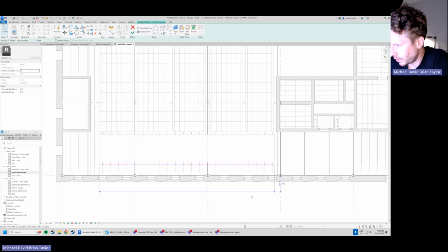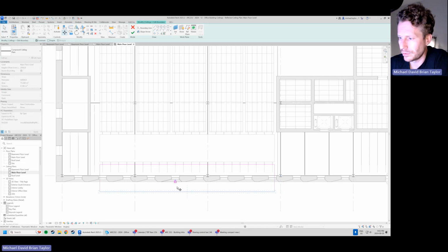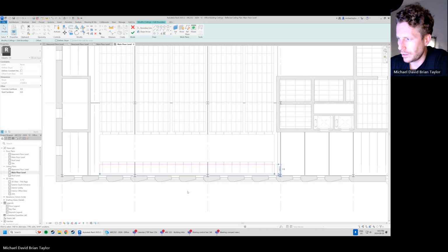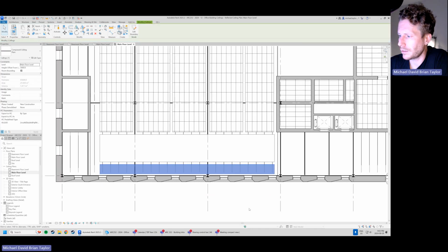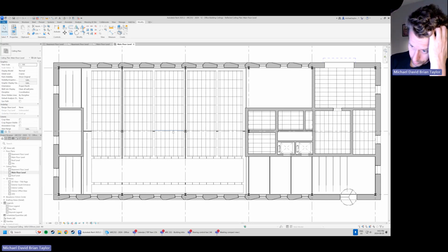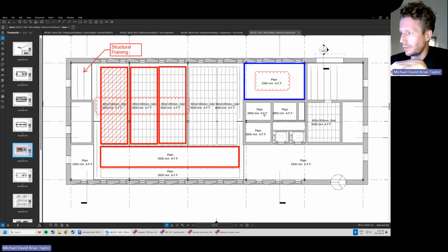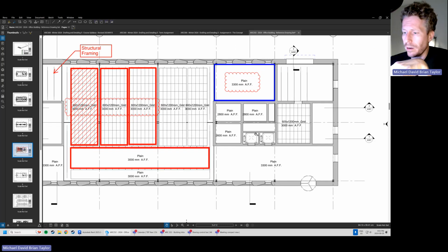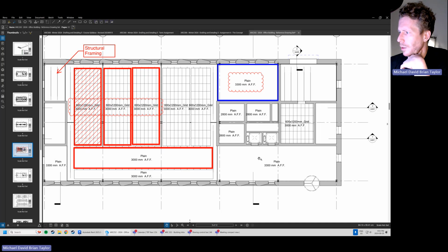Let's just go ahead and we'll just move this up. So the move command up in our modify panel, click move. Somewhere inside, checkbox, good to go. So yeah, these are just some example tools. I think that you guys should be able to put a couple ceilings in here. Try your best to follow along with the existing best in town example here. So do your best to get these families in here. We really only got two families, the 600 by 1200 and the plane.